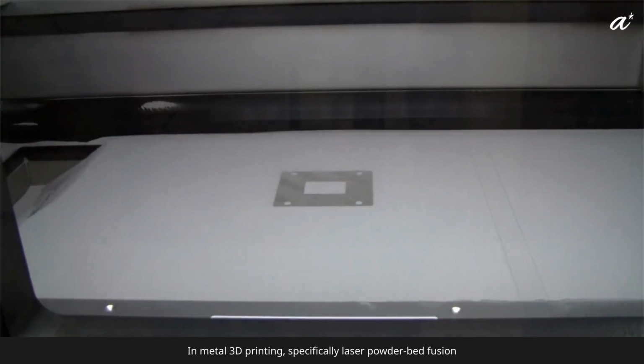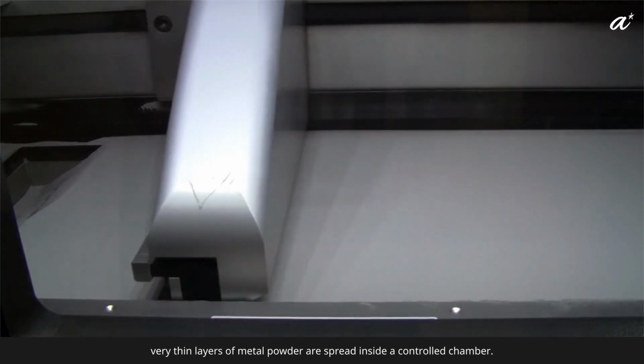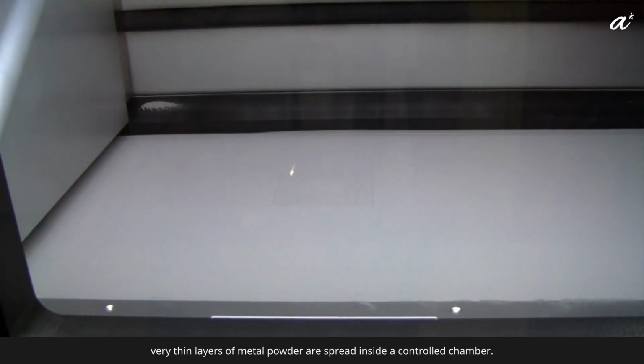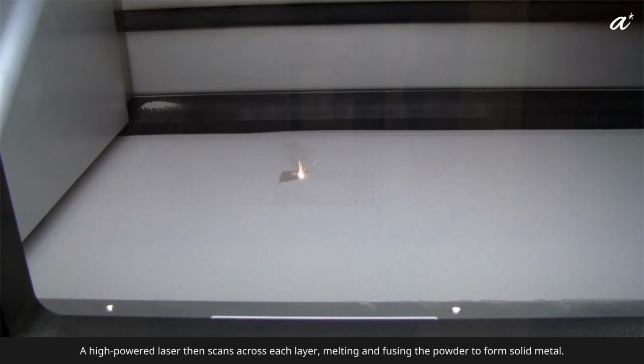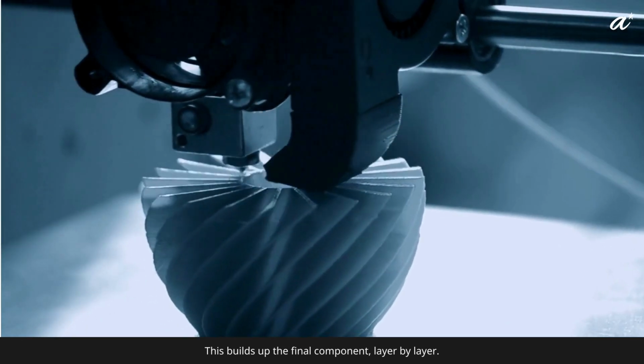In metal 3D printing, specifically laser powder bed fusion, very thin layers of metal powder are spread inside a controlled chamber. A high-powered laser then scans across each layer, melting and fusing the powder to form solid metal. This builds up the final component, layer by layer.